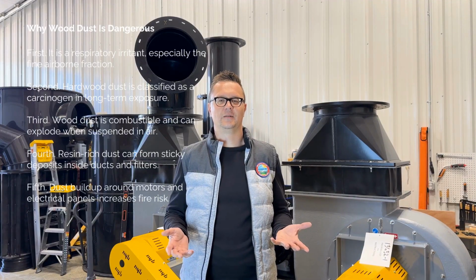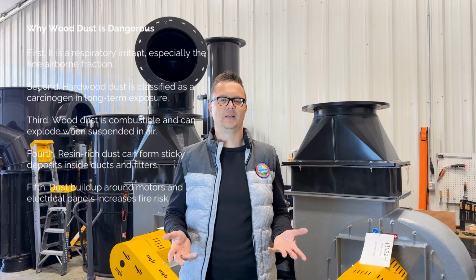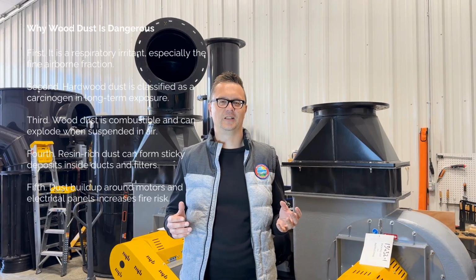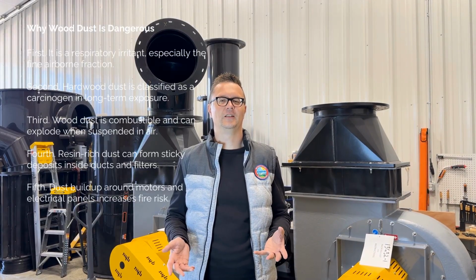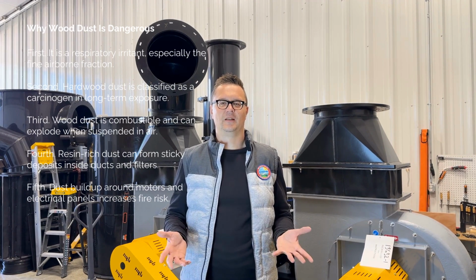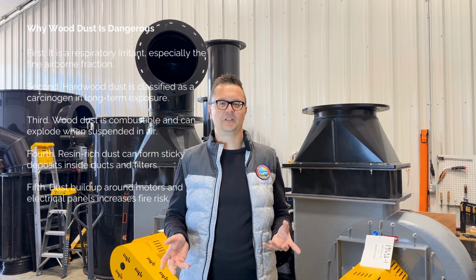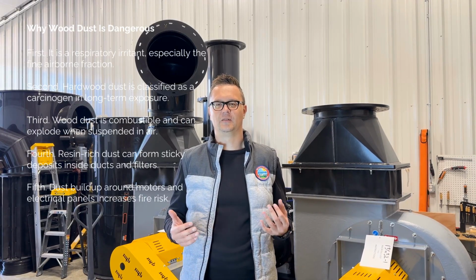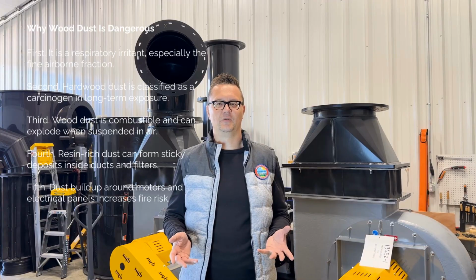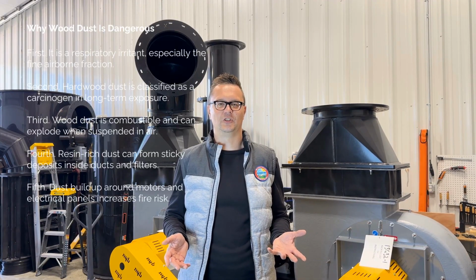Why wood dust is dangerous? Wood dust introduces several hazards. First, it is a respiratory irritant, especially the fine airborne fraction. Second, hardwood dust is classified as a carcinogen in long-term exposure. Third, wood dust is combustible and can explode when suspended in air. Fourth, resin-rich dust can form sticky deposits inside ducts and filters. Fifth, dust buildup around motors and electrical panels increases fire risk. Even a thin layer of dust on a hot surface can ignite under the wrong conditions.